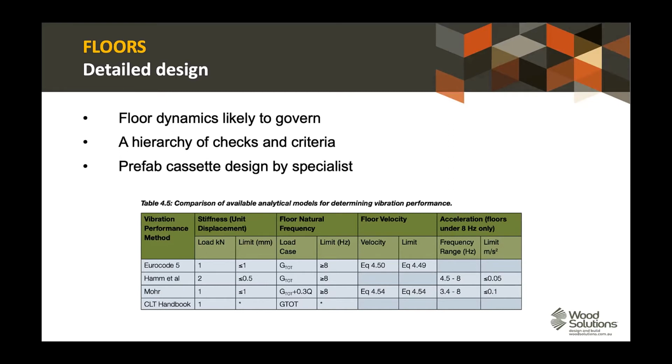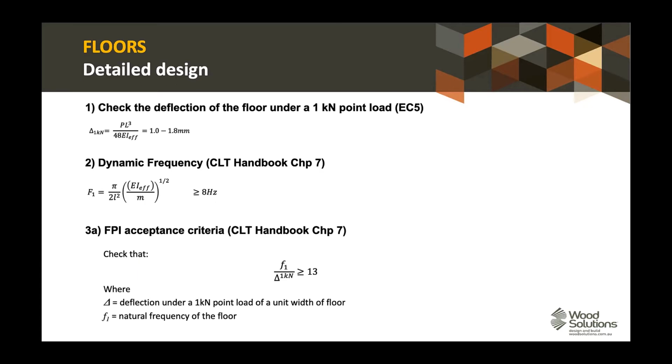But the interesting thing about timber floors is that being lightweight, they can have relatively high frequencies because they're lightweight. But because they're lightweight, they may be less stiff than heavier weight things. But also, importantly, because they're lightweight, the accelerations can be our biggest problem. And from a dynamic point of view, the acceleration is what we perceive. So an acceleration check is the most thorough, albeit the most difficult, but the most thorough check we can do on a timber floor structure.